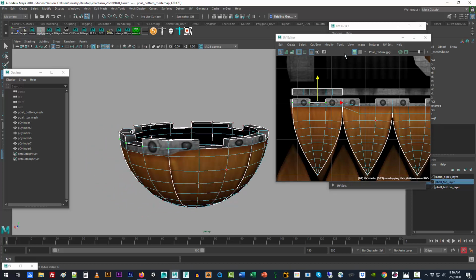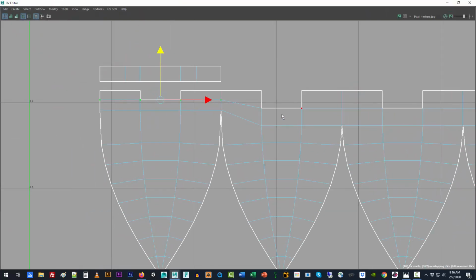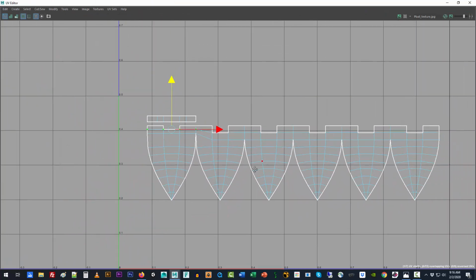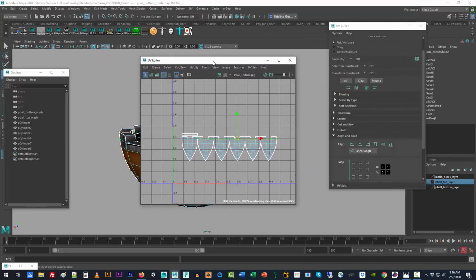And using this same trick, now that we have a definitive height in the up and down direction for these two levels, turn the image off, go full screen with your UVs, and we can use our little trick, which is we want to grab the one that's aligned correctly and then all the other ones that are not aligned correctly, and do that little trick where we move them up using the UV toolkit. So snap them all up at once.